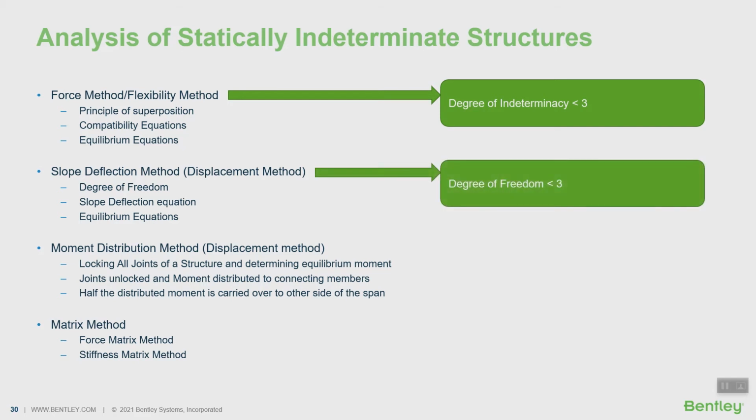In comparison to the force method, slope deflection method requires less work to both formulate and solve the necessary equations, but it is not suitable for a system with very high degree of freedom. In slope deflection methods, additional equations required are formed by relating the unknown slopes and deflections to the applied loads on the structure.